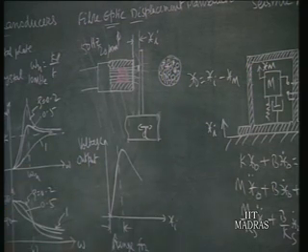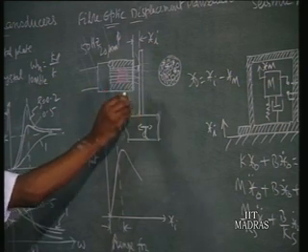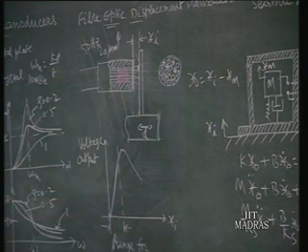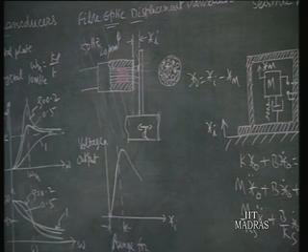The second advantage is that it is a non-contact type of transducer. So the measuring instrument doesn't touch the moving member. Hence you find no loading effect in such instrumentation. That is the main advantage of fiber optic displacement transducers. Many American firms are making this type of transducer.